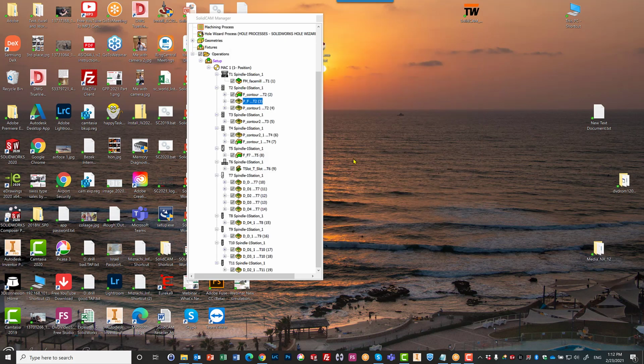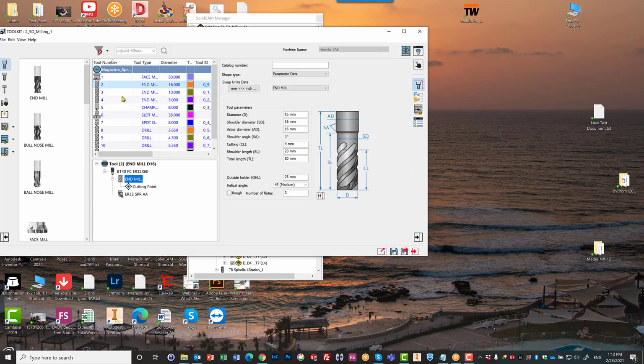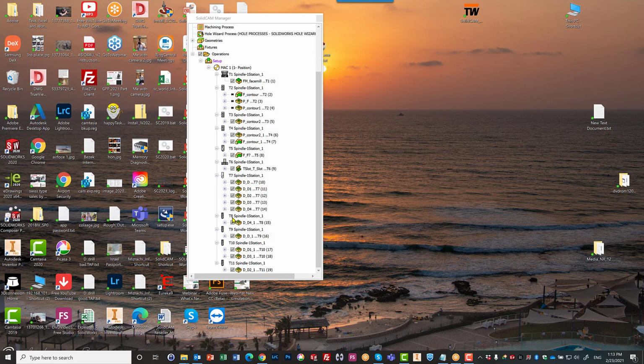That's the way this particular tool has. Now, I'm going to go out of the operation for a moment, going to go into my toolkit. If I open my toolkit, I'm going to go to that particular tool, and I'm going to say, you know what? I have a new tool now that I have on the shop floor, which I didn't have before, and the total cutting length of this tool is not 4 millimeters, but it is at a total of 8 millimeters. So I can change that to 8 millimeters now and save and exit. All this can be done inside the Shopfloor editor.